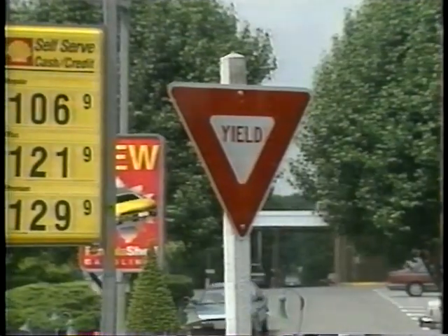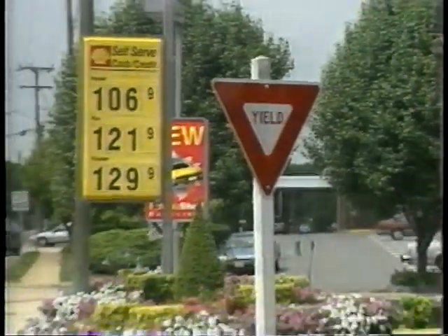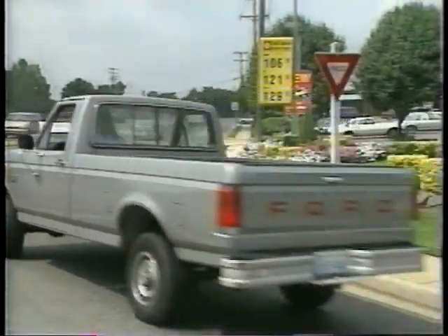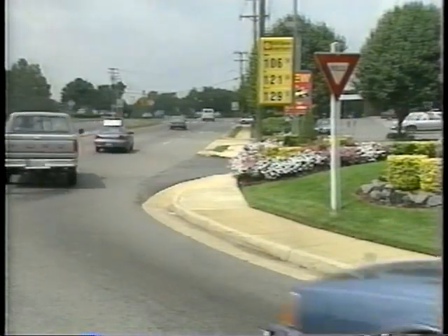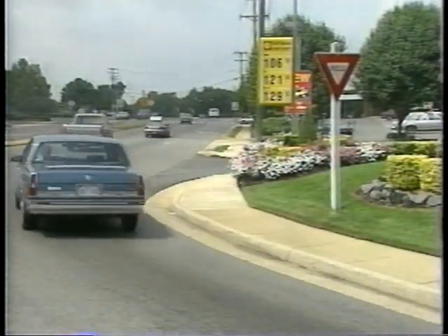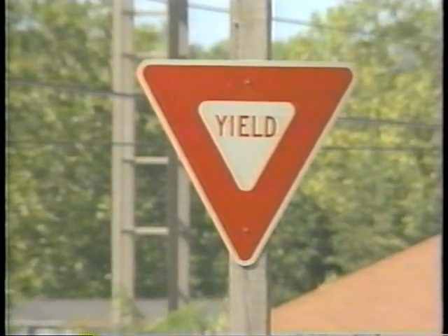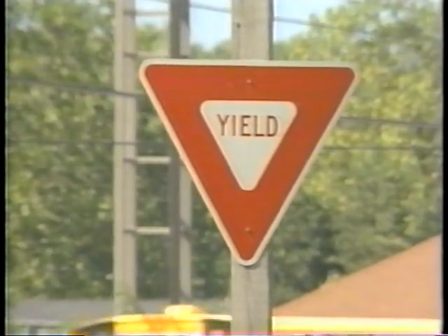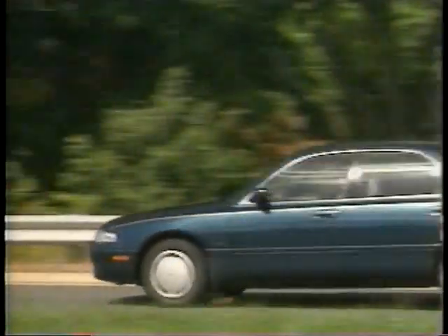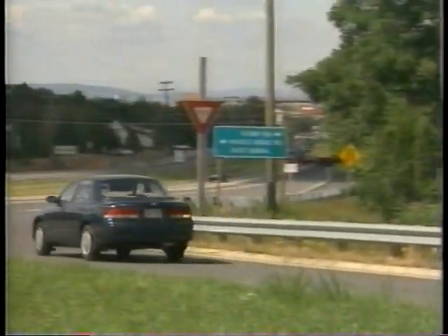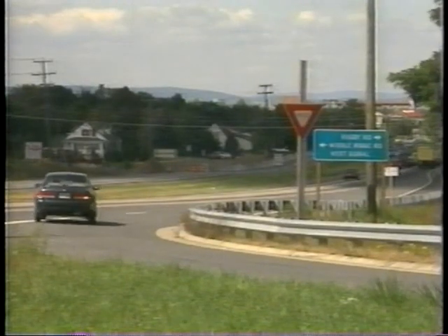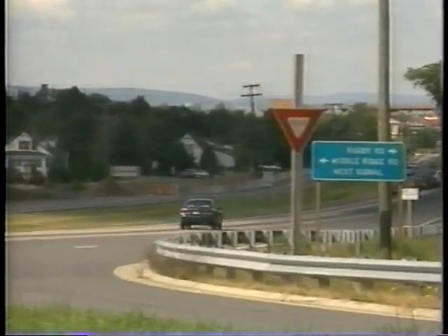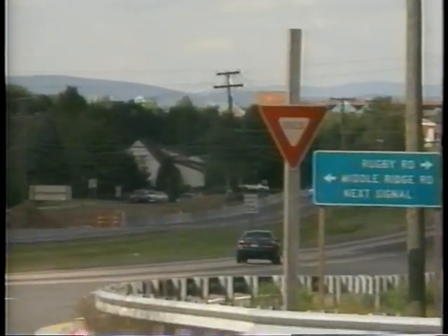At an intersection where it is usually not necessary to stop, the systems provide a yield, or in the European system, a give way sign. This sign is triangular and usually 91 centimeters on each side. Sight distance and approach speeds at the intersecting roadways determine whether or not to use a yield sign rather than a stop sign.